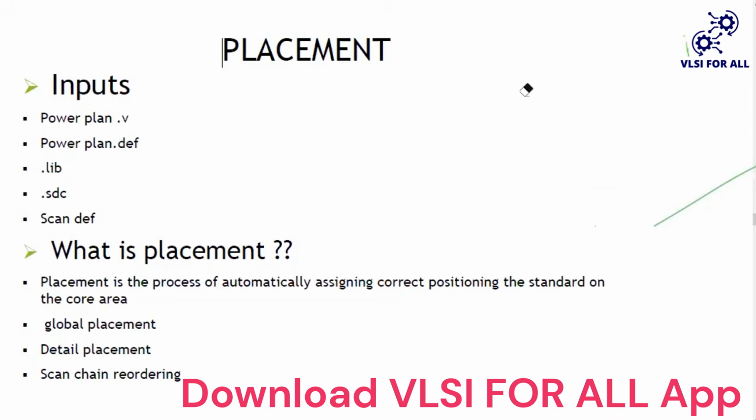Thank you so much. So let me take the queries. Does anyone have any doubt? Any query? Halos and keepout margin are both the same, but some small variation is there. First I'm explaining the keepout margin. It will be useful to create for macros, and in case it will be useful for some specified cells.